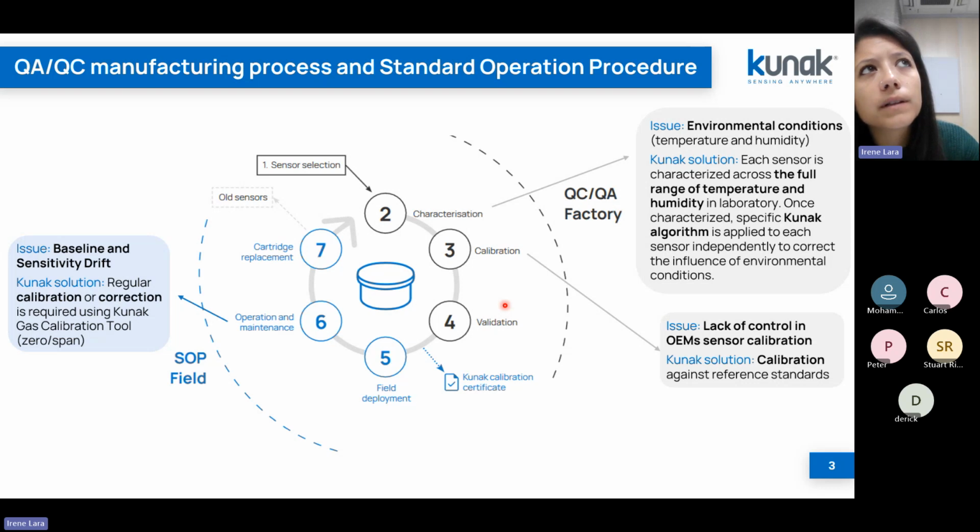So we have some technical specifications for each sensor. I don't remember them by heart. I think they are up to 40 degrees. I'm quite sure. And the accuracy depends on the temperature, but also the humidity transients. It's not the same if we have 40 degrees with not too much variation of humidity, or if we have that with high humidity transients. That changes the effect that is produced on the sensor signal.